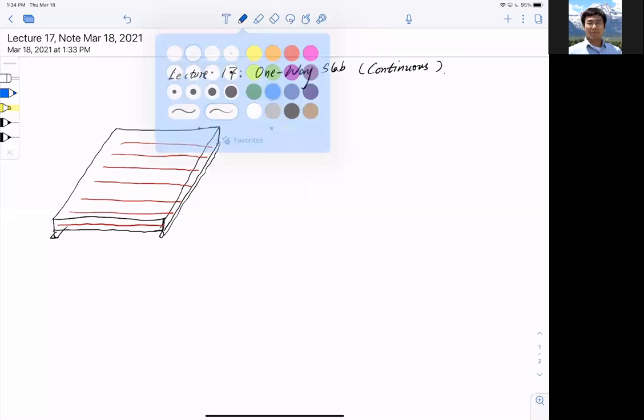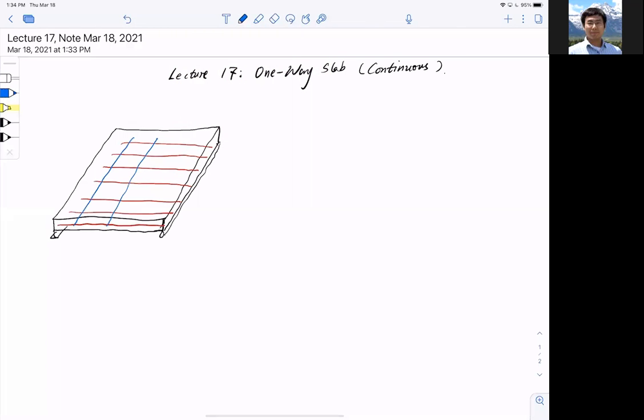And we have just talked about temperature reinforcement. So let me draw the temperature steel very sparsely for the other direction. So this is flexure. For the moment diagram, let me use a different color. Apologize. Simply draw the uniformly distributed load like so. And the moment diagram is even easier. It just has a maximum moment somewhere in the middle and is positive.